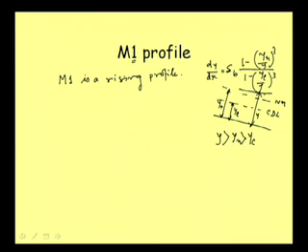And then if it is like that, this ratio yn by y is becoming a fraction, as yn is smaller than y. The cube of the fraction is definitely less than 1, and 1 minus something less than 1 is positive. Here also, yc by y being less than 1 is a fraction, and the cube of the fraction will be definitely a fraction, and 1 minus a fraction is also positive.